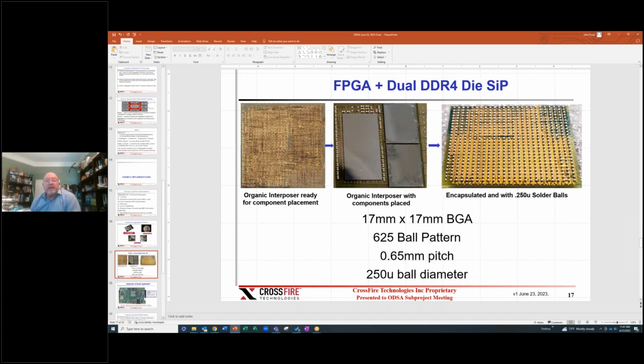This is a system and package device that we did. We also have a thin film interposer that we developed that's in our technology portfolio. We're really not emphasizing it that much, but what we have found out we need to do is to mount it onto a substrate for power delivery purposes, because signals and traces and power traces have much different requirements there.